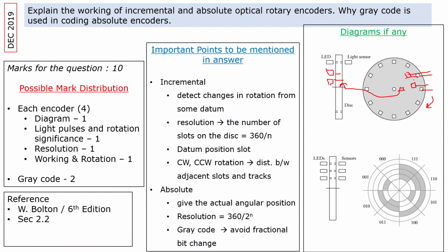So if that series is coming, then we can understand that it is counterclockwise. So I repeat, if the signal comes from outer then middle, in this particular example, that will be clockwise, and if it is middle then outer, that is counterclockwise.